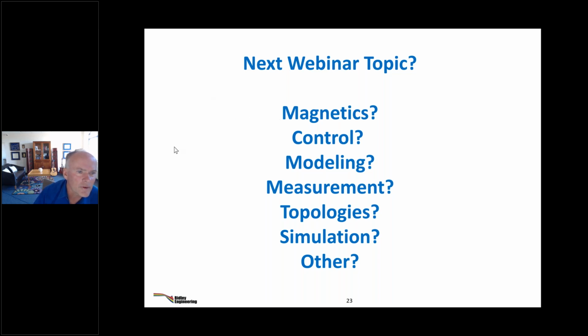If you have a desired frequency range, how do you go about it? I don't know, that's kind of the output. The frequency range is the result. When you're done, you choose the minimum, you end up with what the maximum has to be. So you can't really start with that frequency range and then go backwards the other way. If you want a narrow frequency range, just restrict your input voltage range.